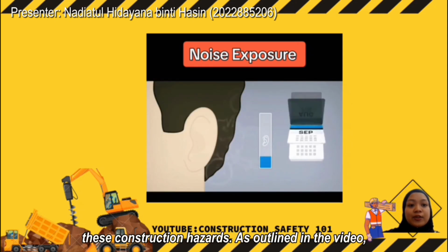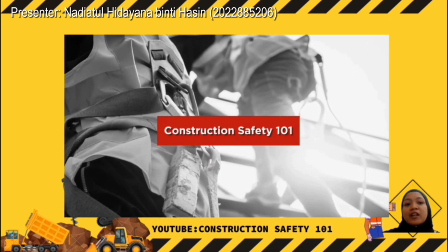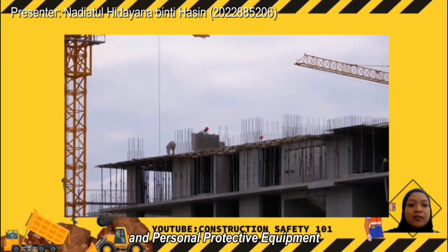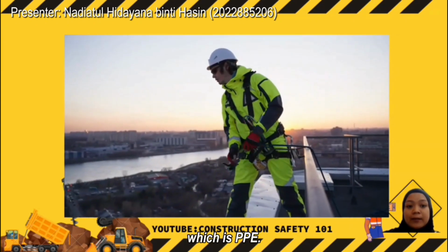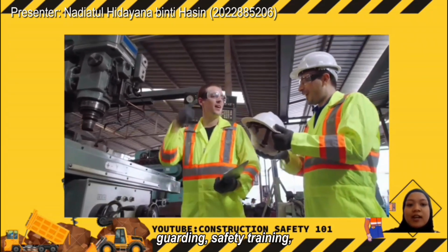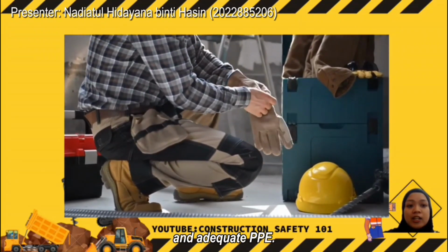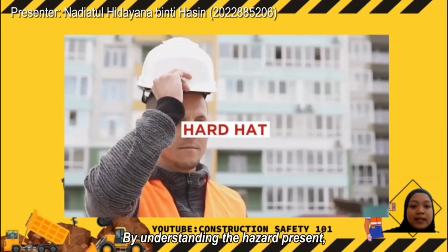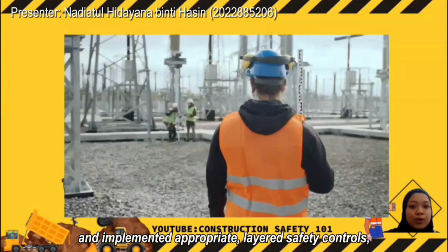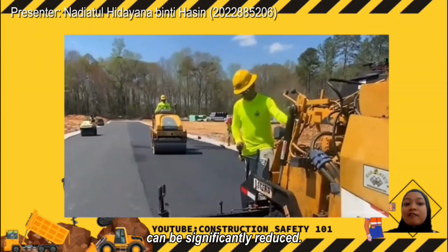As outlined in the video, these controls include elimination, substitution of hazard, engineering control, administrative procedure, and personal protective equipment, which is PPE. Some examples are using fall arrest systems, machine guarding, safety training, hazardous substance substitution, and adequate PPE. By understanding the hazards present and implementing appropriate layered safety controls, the risk to construction workers can be significantly reduced.